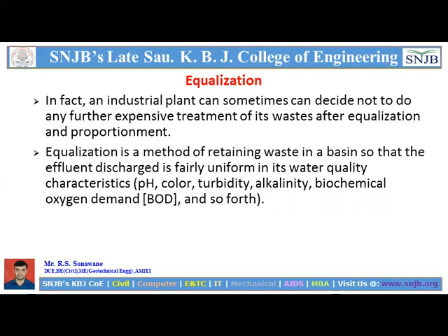So equalization in general means retaining the waste in a particular basin so that the effluent discharge will be fairly uniform. You know that water characteristics are mostly physical, chemical, and biological. To maintain these characteristics or quality of water, the waste should be retained in the basin, and this overall method is called equalization.